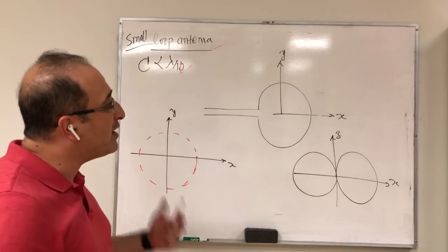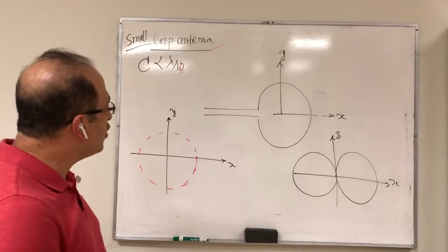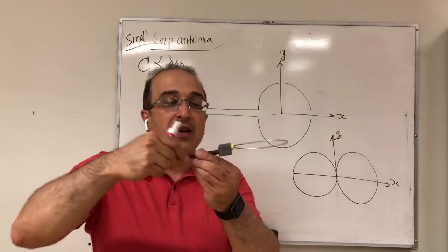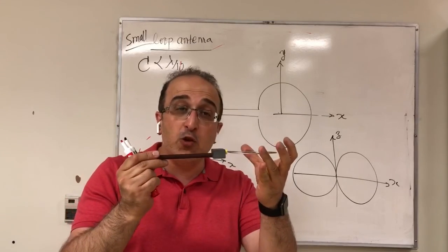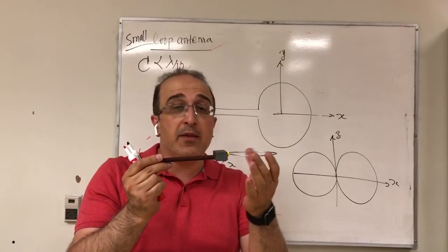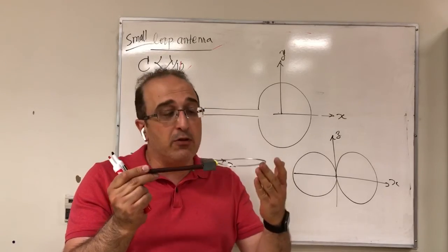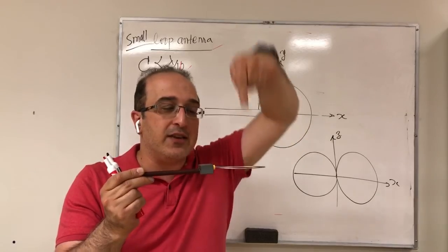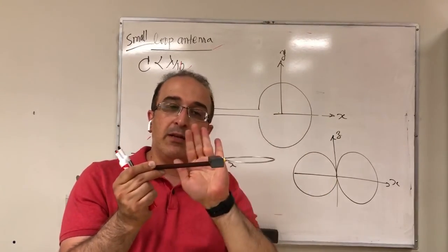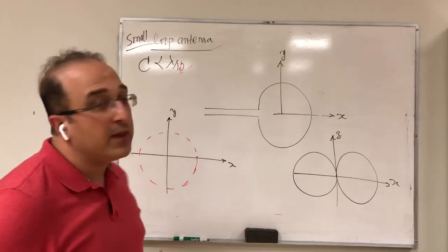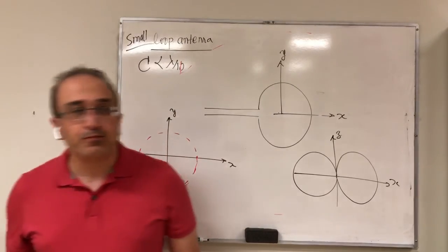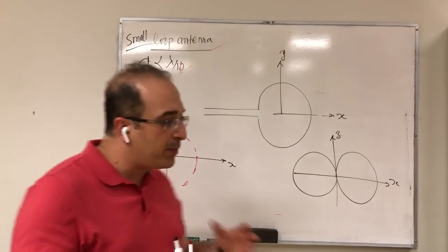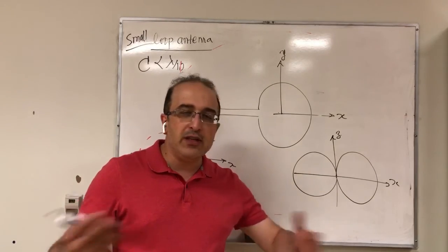So this is going to be very similar to a dipole antenna. Dipole has exactly that. So if this is my loop, and assuming that this loop is small, and small depends on the frequency, so you need to choose a frequency for which it is small. Then if it's small, along the axis, no radiation. If you go around, similar radiation, which would be this case over here. So that's the discussion on my small loop antenna based on this type of intuitive discussion.